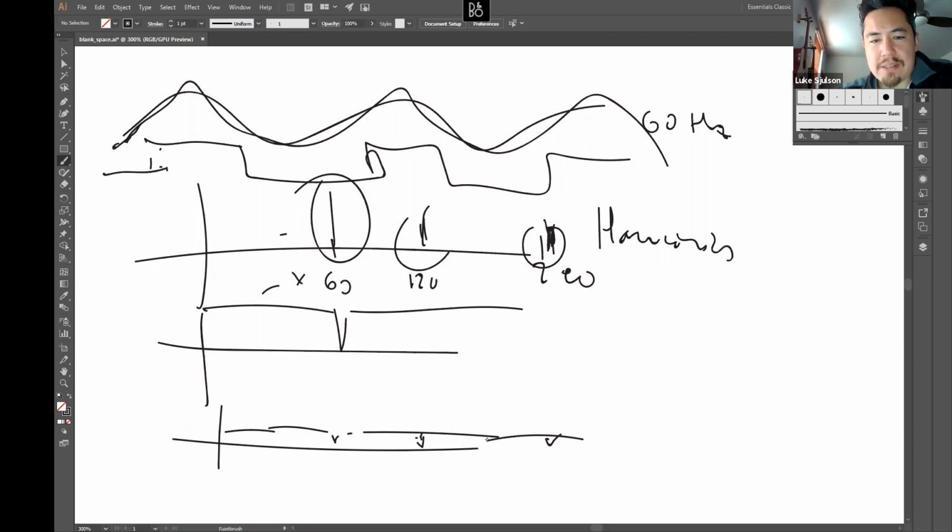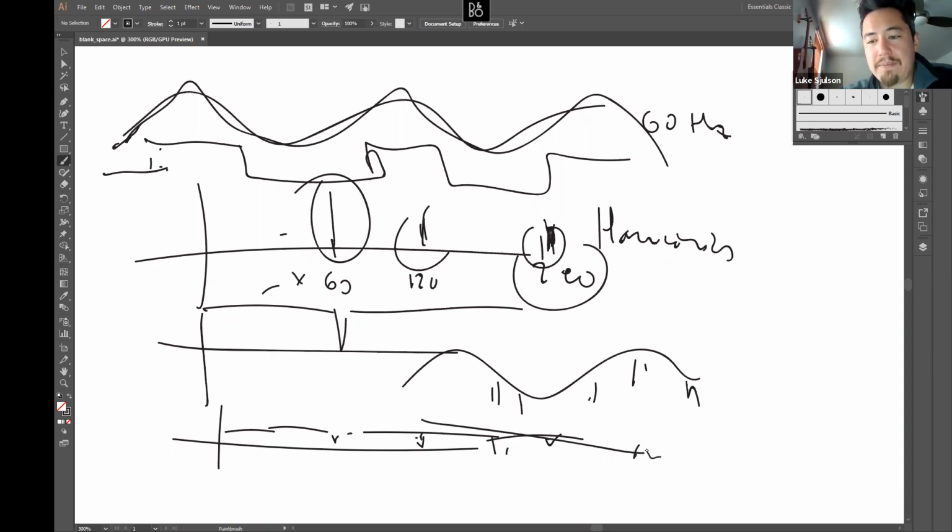What I'll say about it is that it's useful in certain situations and not others. A situation in which it's useful is if you're recording something like action potentials, where virtually everything that you need to know about the action potential waveform is above 300 hertz. It's in a range between, say, 300 hertz and 8 kilohertz. It is possible you could have harmonics that get up into that range, but if you filter out 60 hertz, and say the original signal looks like this, that's at 60 hertz, and you have spikes on top of it, then you can notch filter at 60 hertz, and you'll get your perfect action potentials, and that's fine.